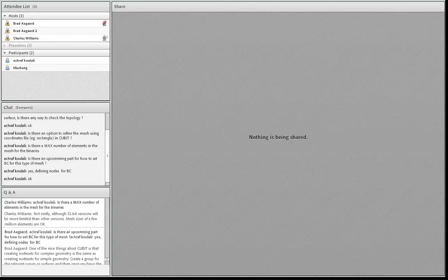Yes, an exercise for the reader. The mesh for this sizing function example is very similar to the ones for the 3D hex 8 examples. If you get motivated, it might actually be interesting to take this mesh and then run one of those examples. You would have to change it a little bit because in the 3D hex 8 mesh, the fault goes all the way through. But that would be an easy thing to change.